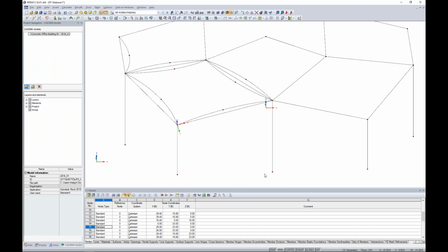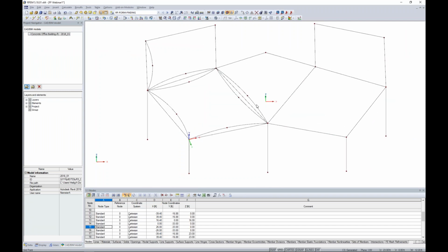So deactivating this grid down here at the bottom, I have these cable elements shown here and I'd like to show them on the other side. So rather than going through that entire process again with our user-defined grid, we can hold down our control key to select what will be these cable element lines and take advantage of our mirroring tool.